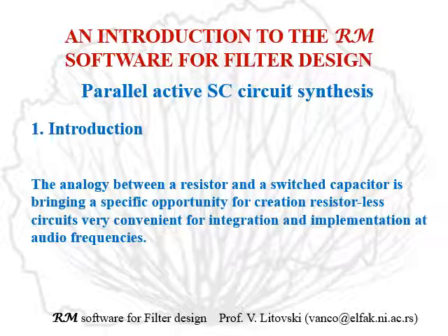And since the resistor additionally has parasitic elements and it is noisy, one would be very happy to substitute them with something else which occupies less area and preserves accuracy, which is also a problem with large resistances.